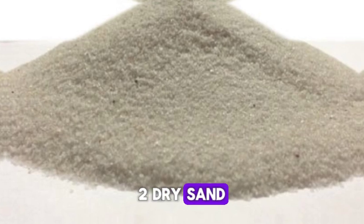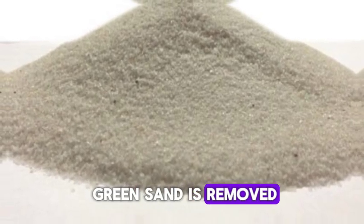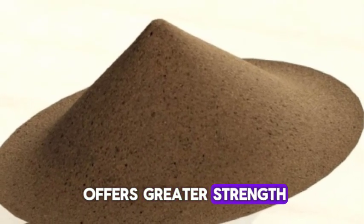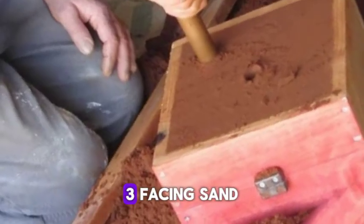2. Dry sand. This casting sand is obtained when the moisture from green sand is removed. It is used for large and heavy casting because the molding sand offers greater strength, rigidity, and thermal stability to the casting.